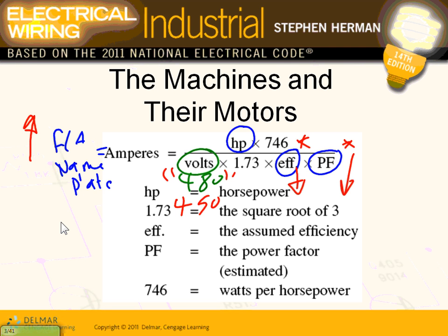If you go to the NEC code book, if the nameplate on a motor says, say, 90 amps, for the same motor, the same voltage, if you go to the book, you're guaranteed you get probably 10 to, I would say, 15% extra on it. 10 to 15% extra to accommodate for all these factors. Is it a formula though, or is it just all I don't know. I haven't figured that out. See if Excel can come up. But from my just running certain numbers, Chris, I would say 10 to 15, maybe 20 extra.